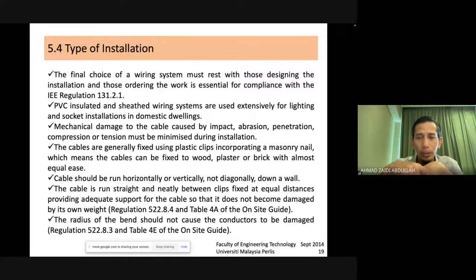And sometimes if you measure or you scan by thermal imager, you can find that there are hot spot there at bend. So normally the fault come at that location. So that's why you are suggested to design bending of cable not up to 90 degree. Okay.